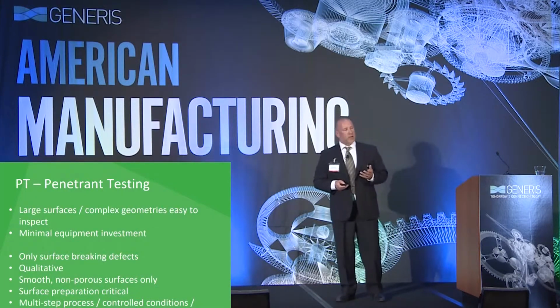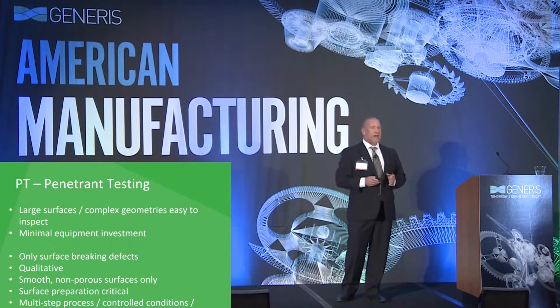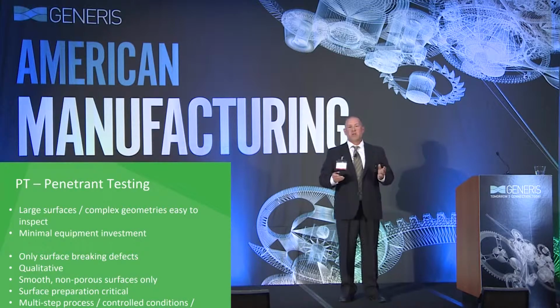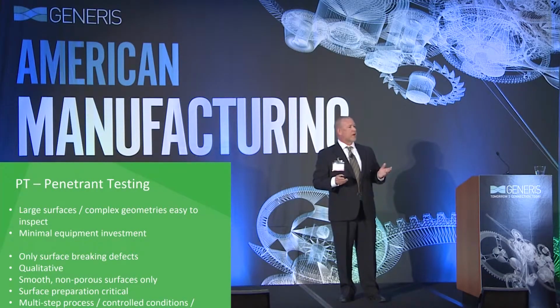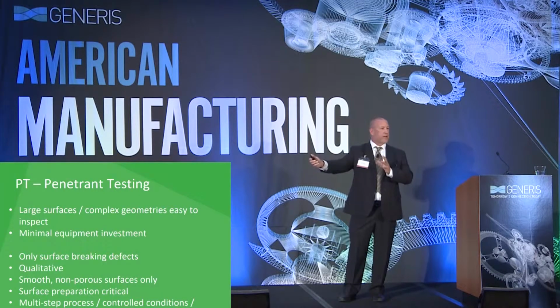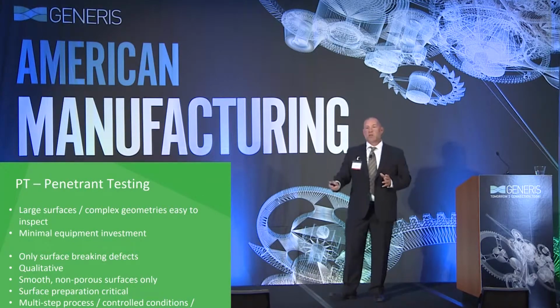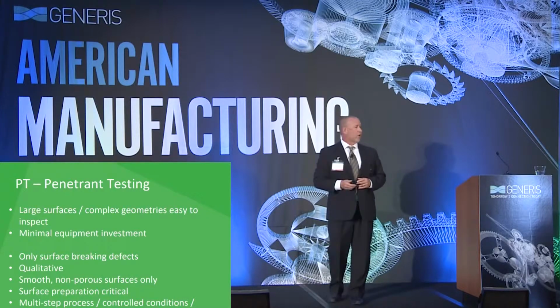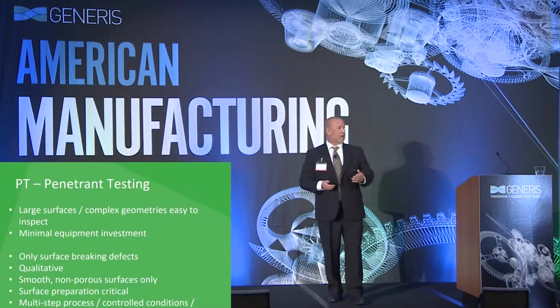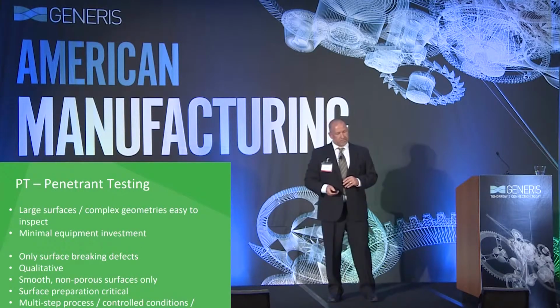In terms of important characteristics, well, penetrant testing is ideal for large, complex parts, complex surfaces, a gas turbine engine blade, a crankshaft in an automobile engine. That's a classic example of fluorescent penetrant. Really complicated surfaces. At arm's length away, I can get an indication that there's a flaw there. What about limitations? Well, you're only going to see surface breaking flaws. If it's a subsurface flaw, can't see it because the capillary action won't get the penetrant that deep into the part. It can't find that crack. It can't reveal that crack. So surface breaking only, okay?